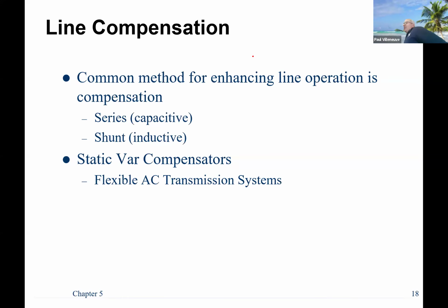And I think this Chester static VAR compensator is 40 MVA rated maximum, but it actually improved the performance of the line. So it actually pushes an additional 200 megawatts on those lines just by adding those static VAR compensators. So for a 40 MVA static VAR compensator, you get a lot of bang for your buck.